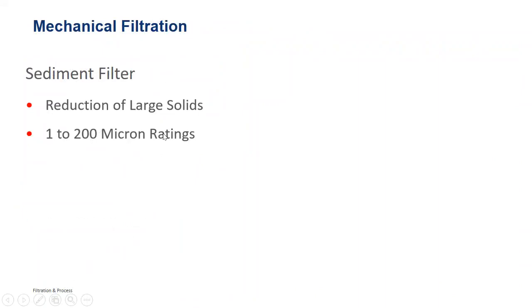We do offer a lot of sub-micron filters as well, but they tend to be paired with activated carbon for more value. But remember, we're typically using sediment filters to protect more expensive treatment train items after it, like backwashing filters, carbon filters, UV, ozone, whatever system after it tends to be more expensive than a sediment filter.